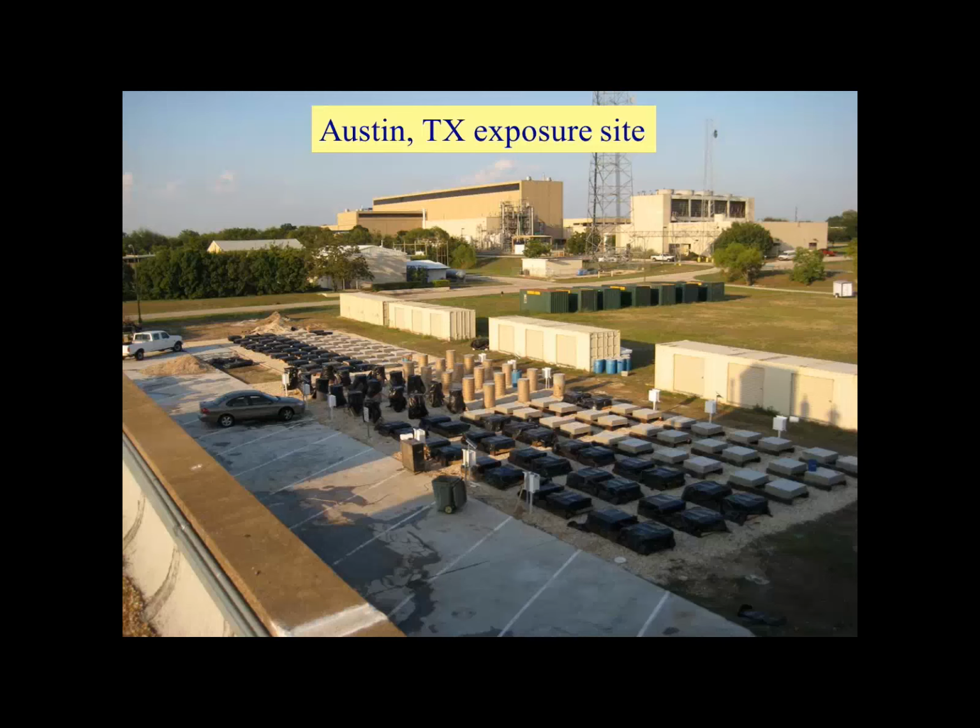One of the critical factors also that I don't think has been evaluated to a good extent at this time is that when we were testing lithium admixtures for preventing ASR, we found that the response to lithium admixture was very much different from one aggregate to another. And as Mike Thomas was presenting last week, we found that in many cases, the aggregates that were found to be responding the best to lithium were those that were the most reactive aggregate material.